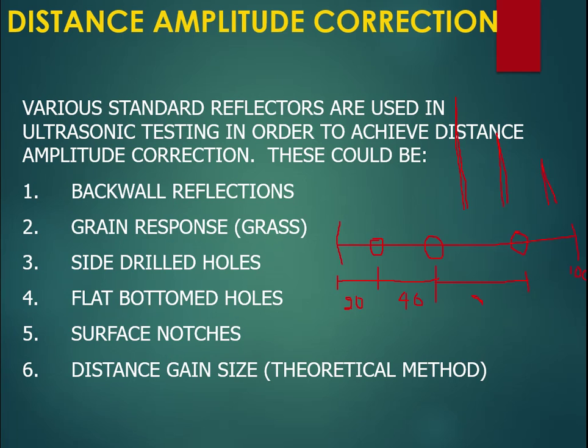In a similar manner, we draw a distance amplitude correction curve by joining all three points in this manner.